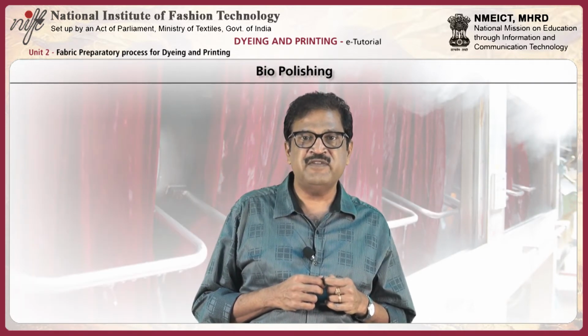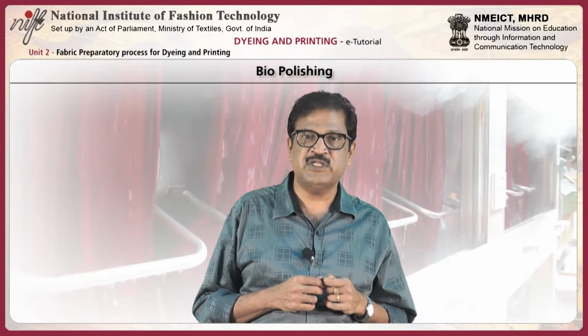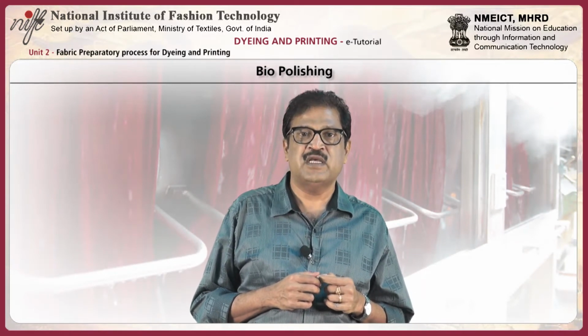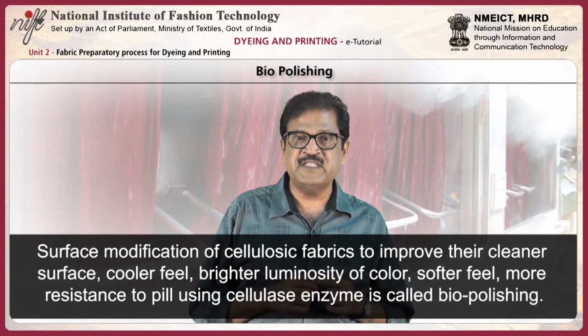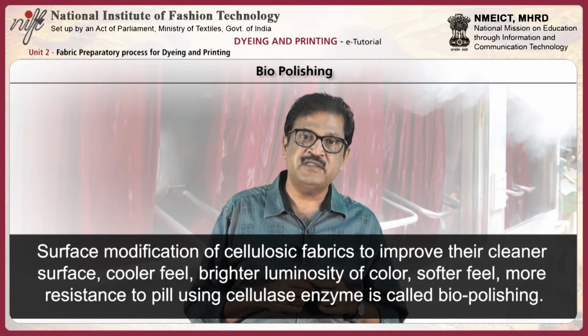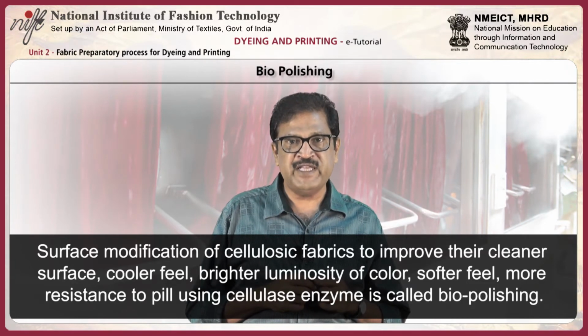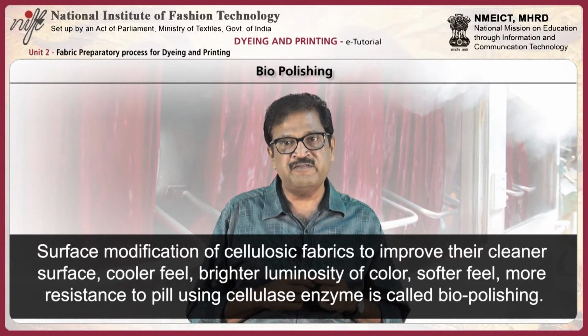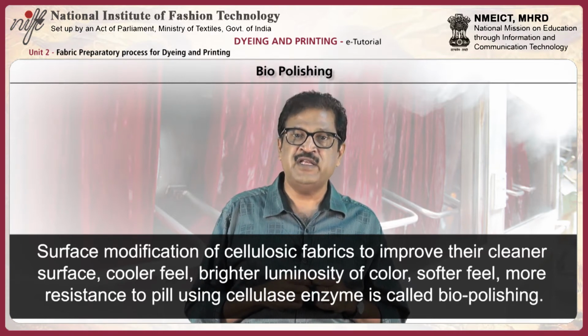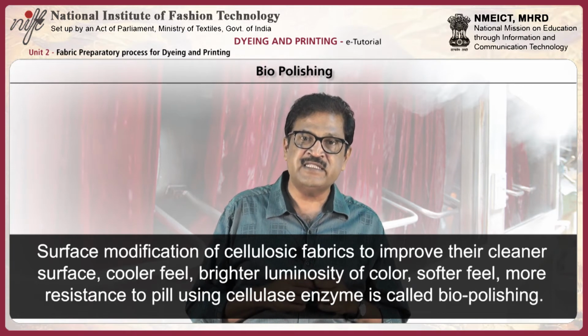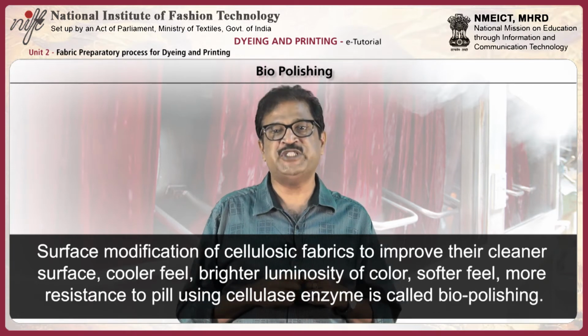Biopolishing is one of the value added processes during the preparatory process. It is a process of surface modification of cellulosic fabrics like cotton, linen to improve their cleaner surface, cooler feel, brighter luminosity of color, softer feel, more resistance to pilling using cellulase enzyme, and is called biopolishing.